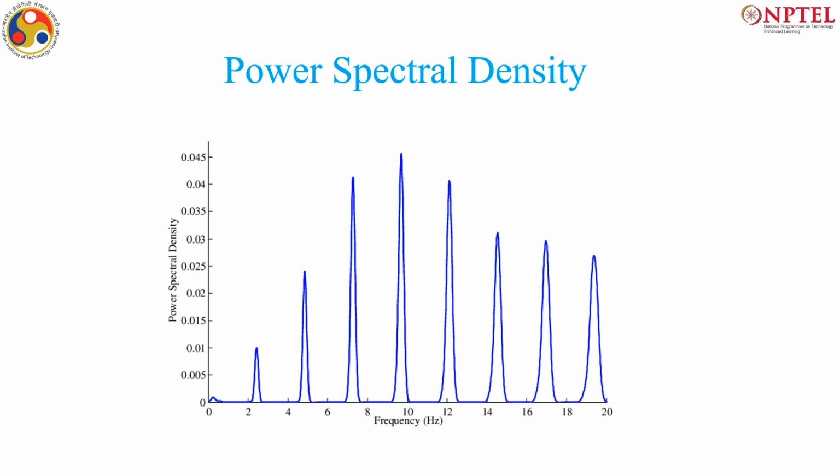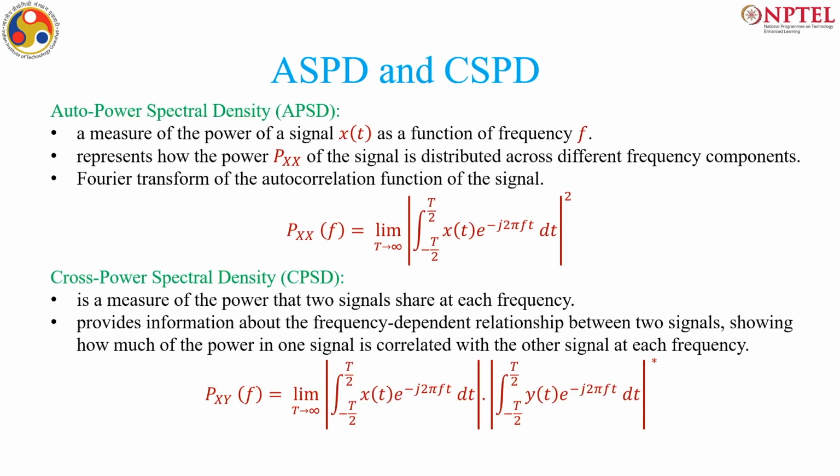Well, this is an example of a power spectral density, which says that these are the dominant frequencies present, or these frequencies have very high power, while others have no component or no power. This is usually obtained using the Welch method, which is why we get a clean, smooth estimate of the PSD. This PSD is also useful in finding the dominant frequencies in the signal, and that is the frequency estimation problem.